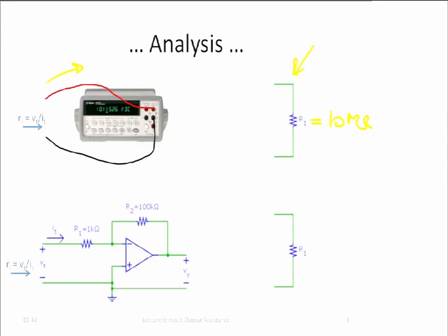Now this amplifier here? Well, let's analyze this. What's the voltage at this node? What's the voltage at this node? Why do we know that? Well, because here we have a negative feedback loop, this minus sign here, and consequently the voltage at these 2 points are equal. Question 3 on the quiz. That's why you could just write down the answer for question 3.